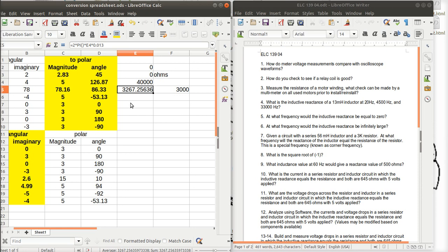I can also just set the equations together. Since I know I'm wanting 3000, that's my inductive reactance. That will equal 2 pi times an unknown frequency times my inductance value, which I gave you. Whoops. I didn't change my inductance value. So that wasn't 56. This is 56. So you see now I'm way too high. Details, details, details. Got to keep track of the details.